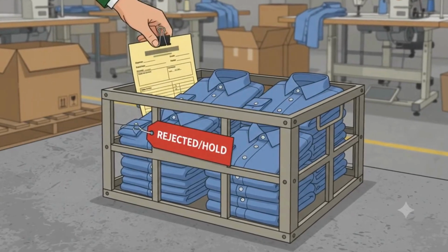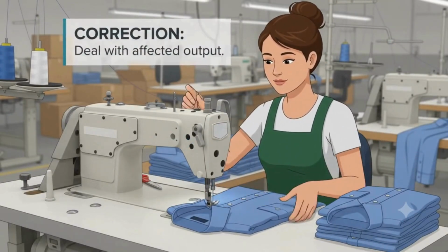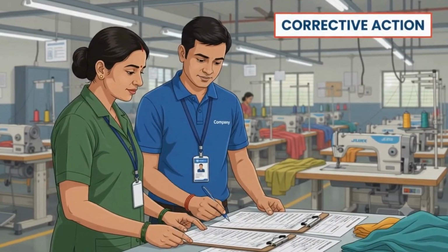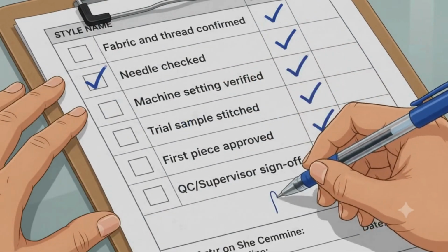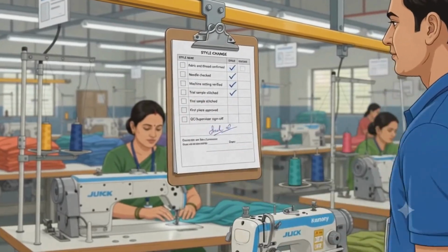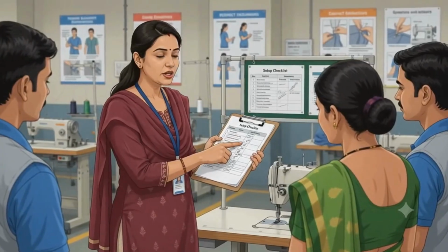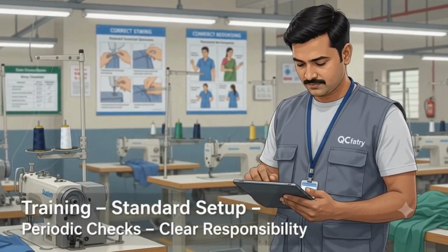Affected garments are segregated, reworked where acceptable, and re-inspected after the machine setting is corrected. Corrective action addresses the identified cause by introducing machine setup verification and first piece approval before bulk production. Preventive controls strengthen the process through training, standard setup practices, periodic checks, and documented responsibilities.